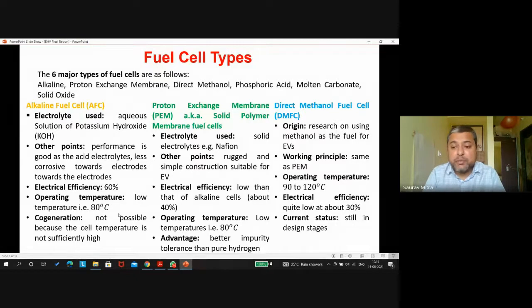That is also another problem because that membrane is actually, you can say, the filter, and it goes bad frequently. There is a little bit of reverse ripple in the output side from the input side. From the output towards the input there comes some ripple, and reverse ripple actually damages the fuel cell and punctures that membrane. So the proton exchange membrane is very sensitive. It is highly costly. So this is the main soft point in case of the fuel cell.